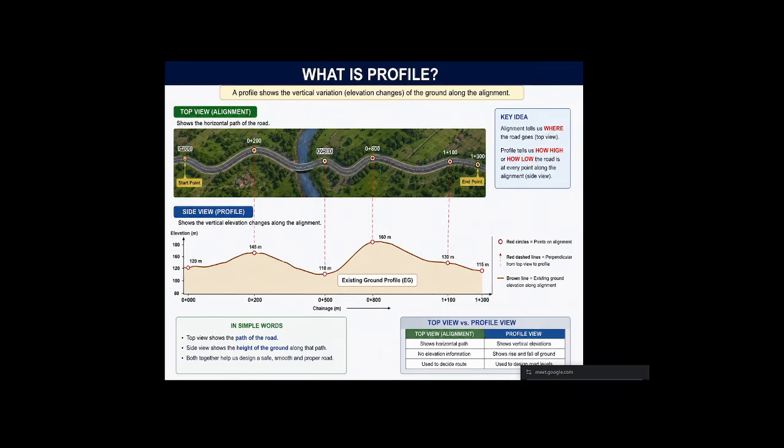Here also, in this image, you can see the sample elevation at different levels. The alignment acts like the cutting line. Okay, we cut the line at the chainage and we check, as per the chainage, what is the elevation here, what is the elevation here, and this is the existing ground, the top surface of existing ground, the level of the existing ground.